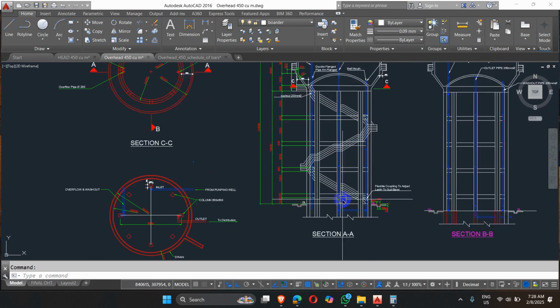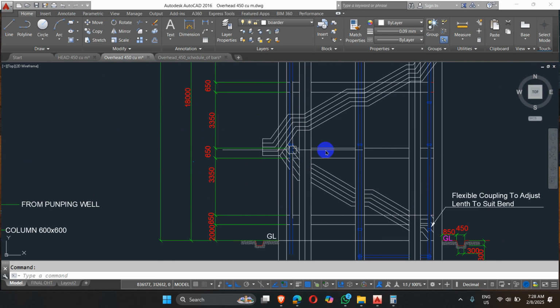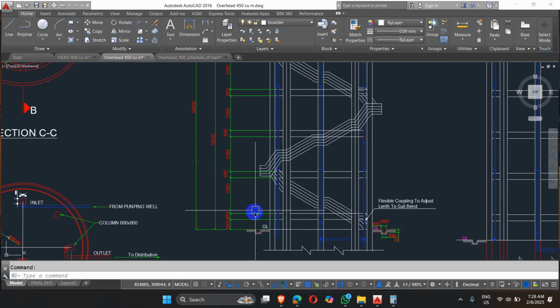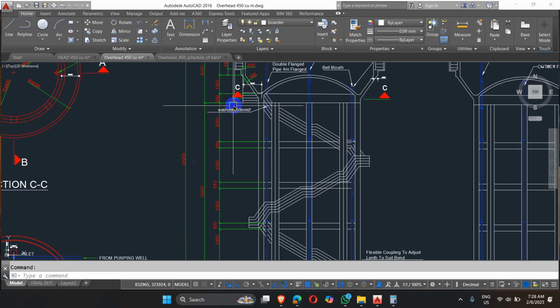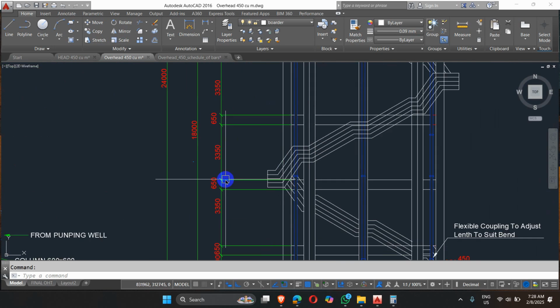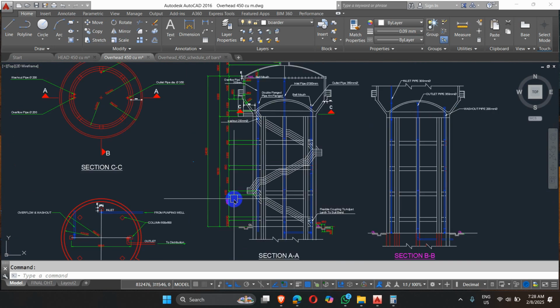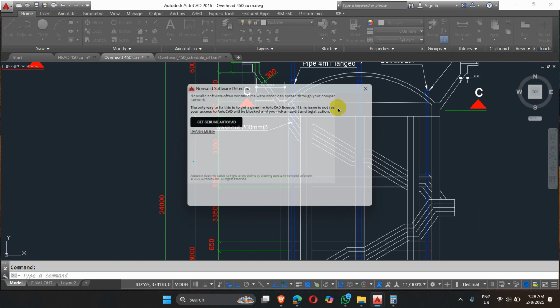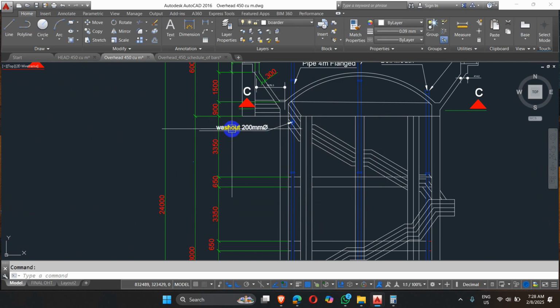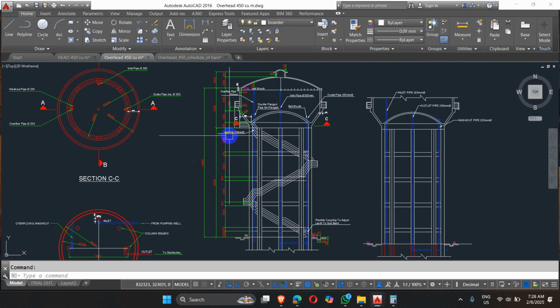And if we see in the sectional elevation, the beams are 500 by 600 mm, which means a depth of 600 mm, four beams of 600 mm, and another top beam where the dome starts, which is 900 in depth. It means the floor height of 3350 plus 650, which is 4000 floor height, and 4250 floor height of one story.